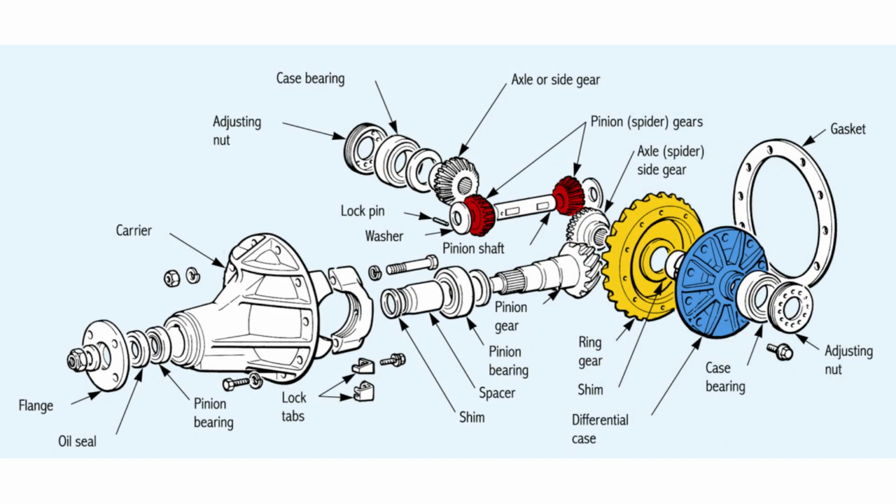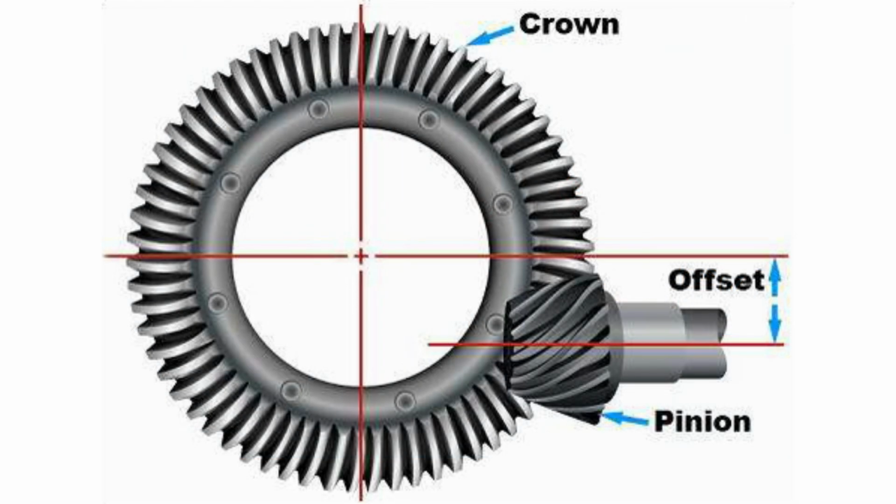The drive shaft applies torque to the drive pinion gear that meshes below the center line of a ring gear. This type of gear set is called a hypoid gear set and requires gear lubrication specifically designed for this type of service. The ring gear mounts onto the differential case.